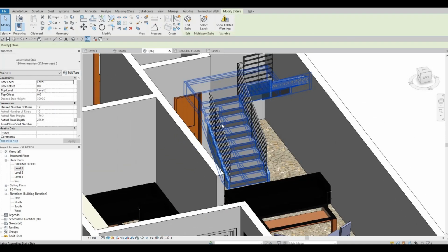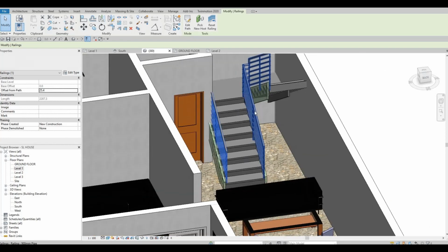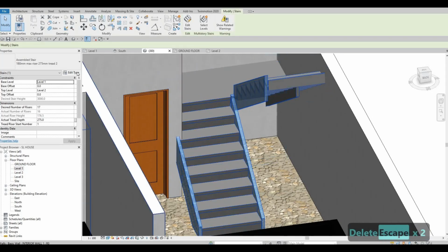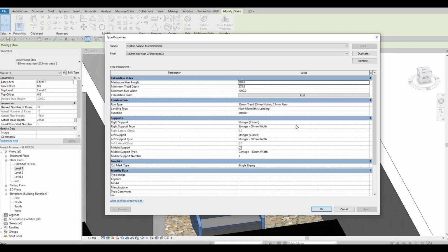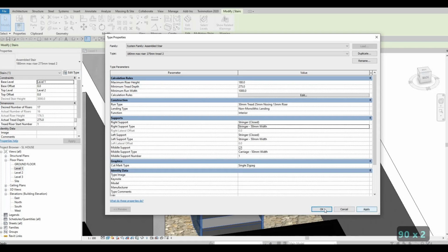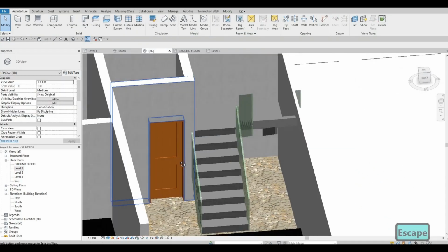And the good thing about that is we can actually remove our railing. So actually we don't need this railing because we can modernize this one. So edit, and then we could make the changes right here again. So total depth, total width. So this one we could put it at 25 or make it 30. In terms of total depth, we could have this one as around 900. And let's see how it changed. And as you can see, it conforms to the building like that.